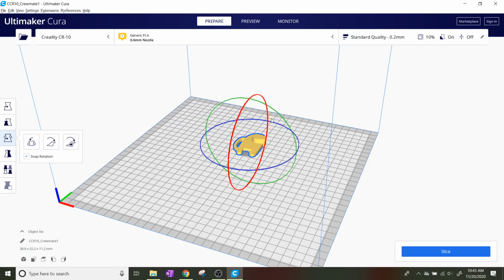The 3 rotational ones are normally called roll, pitch, and yaw, and which is which depends on the actual object you're dealing with. Pitch is normally the up and down direction. Try to think of an airplane. Whenever you pitch up or pitch down, that's the airplane rotating up or down. The roll is it rotating to the left and to the right. And then the yaw is the Z-axis rotation.